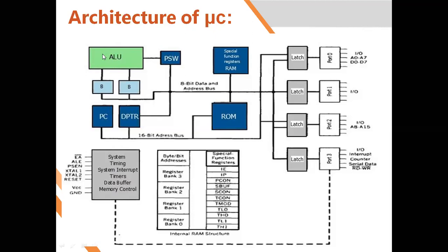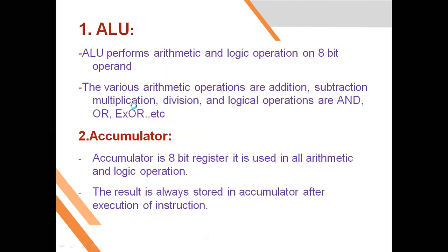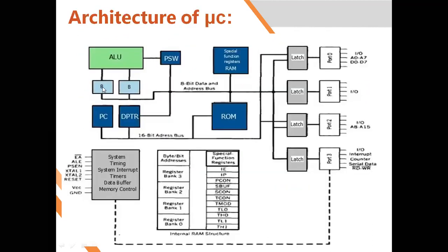Is there any doubt in ALU? No, ma'am. Okay, next one is the A register, which is a fixed one. A stands for accumulator. It is 8 bit long. What is the use of the accumulator? It is a very important register because in any arithmetic and logic operation, the first operand must be in it. An operand is the data on which we perform the operation.